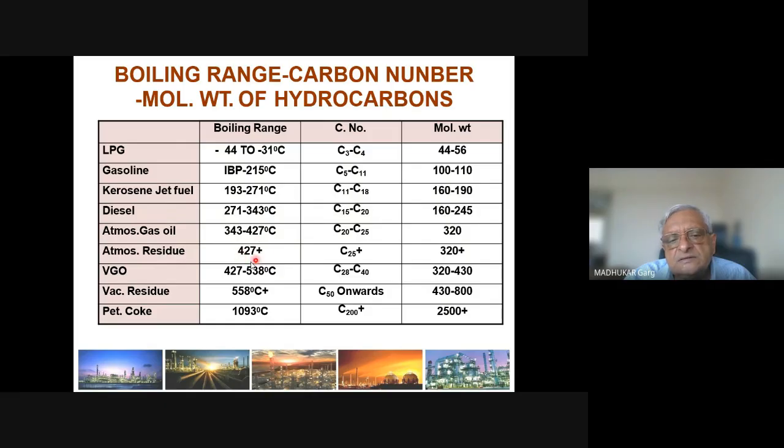This is something that will not boil at atmospheric pressure. And if you start heating it up above 360, 370 degrees Celsius, then hydrocarbons tend to crack. I'll repeat. Even this atmospheric gas oil, although it is called atmospheric gas oil, is distilled out under vacuum so that the distillation temperatures are low. So basically, atmospheric residue is something that cannot boil at atmospheric pressure, because if you try to heat it up above 360, it will crack. It will not boil, and it will crack to some olefins or some other hydrocarbons.